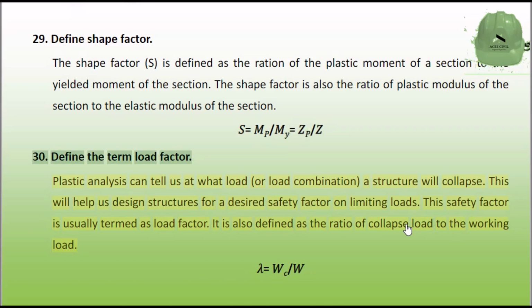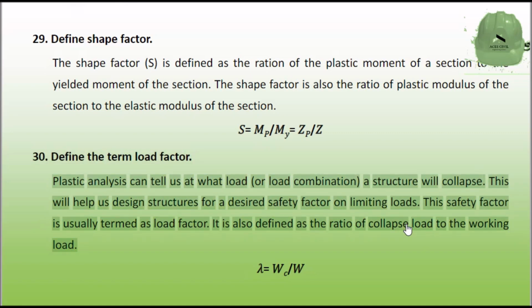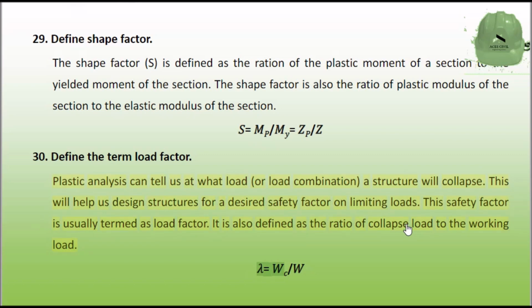Define the term load factor. Plastic analysis can tell us at what load, or load combination, a structure will collapse. This will help us design structures for a desired safety factor on limiting loads. This safety factor is usually termed as load factor. It is also defined as the ratio of collapse load to the working load.